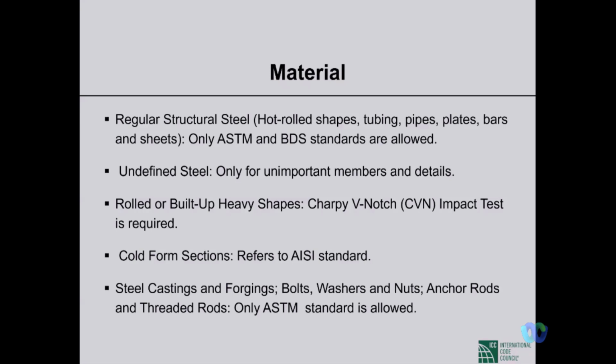They have their own standards. But in Bangladesh, if we want to design steel structure, we must follow material standards ASTM and BDS. So what is the choice? The choice is wherever the place we import the steel sections from, but those sections must pass through all the tests mentioned in ASTM. So that is a must.